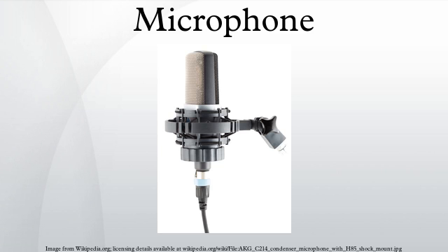A supercardioid microphone is similar to a hypercardioid, except there is more front pickup and less rear pickup. While any pattern between omni and figure-8 is possible by adjusting their mix, common definitions state that a hypercardioid is produced by combining them at a 3:1 ratio, producing nulls at 109.5 degrees, while supercardioid is produced with a 5:3 ratio, with nulls at 126.9 degrees.